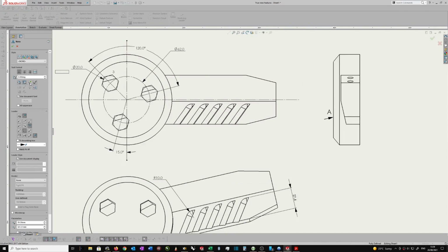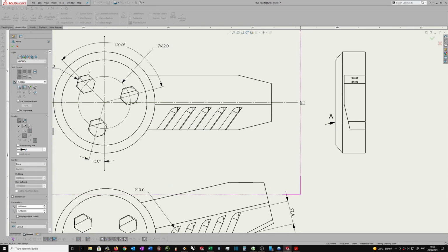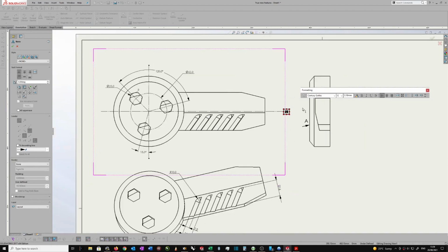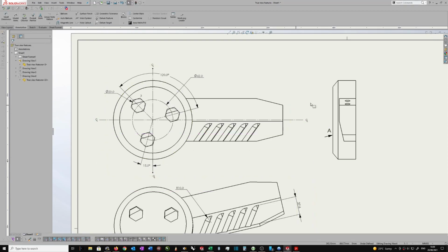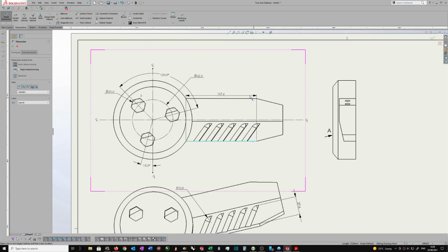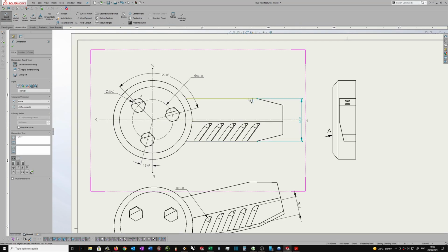Place an annotation, center line. I'm going to take off or push the no leader button, and here I need to click, and don't do anything else, just click again somewhere else in the drawing if you want to place it again. Click, click, so you click twice, and then when you're ready to finish, you hit the escape button. So there my center line marks are in place. Let's put these dimensions back in. So that's good. And that one's good.